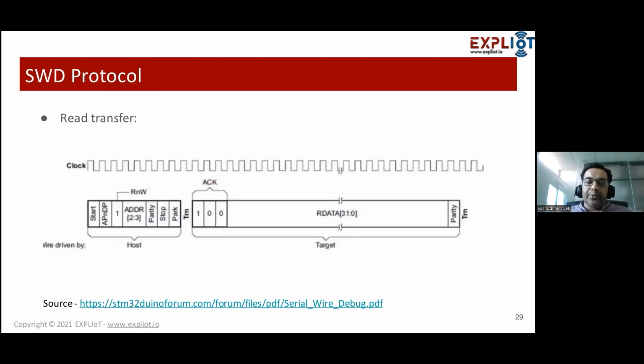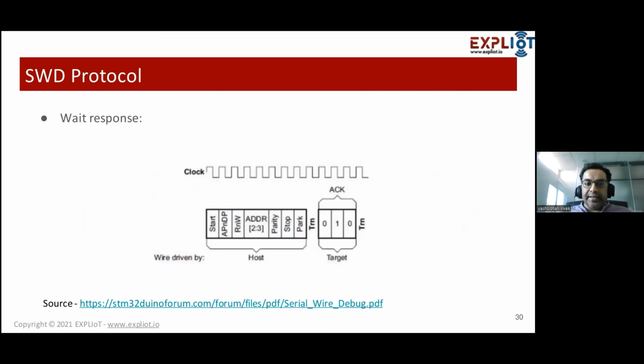On the other hand, when you look at the reading part, the main change is this particular bit, the R and W bit, right? That way reading and writing can happen. Now, there is one more thing associated with SWD, sorry, not JTAG, SWD: the wait response.